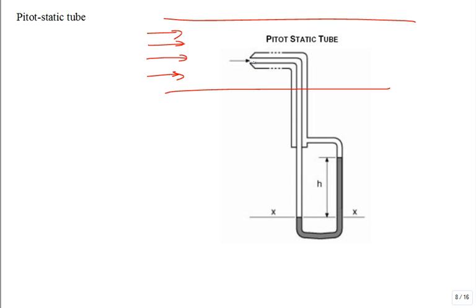I'll color code it blue right here. And there's air, if this is measuring air, there's air in this tube that goes down to the center until it hits a liquid layer, a liquid surface. Maybe that liquid's water, H2O, that's shown here. Water. Could be mercury, but in air systems it's often just water.